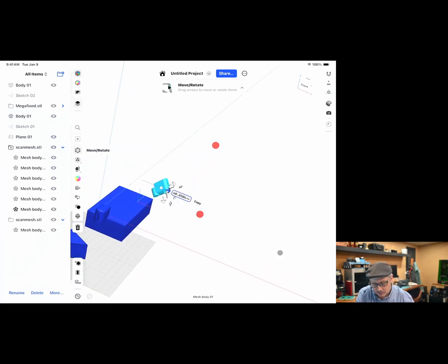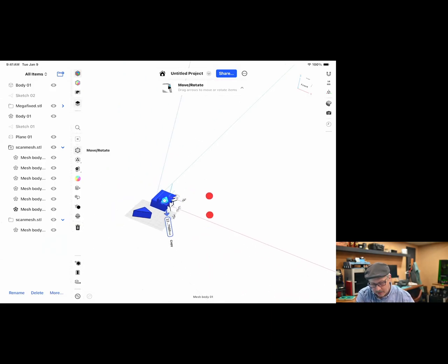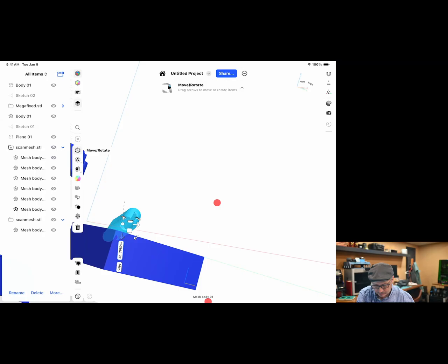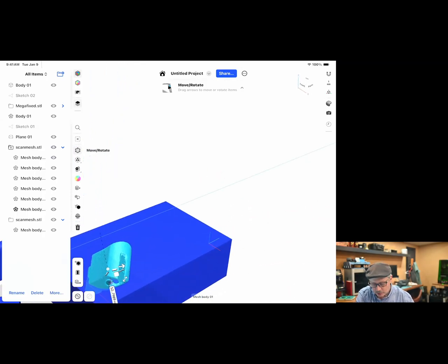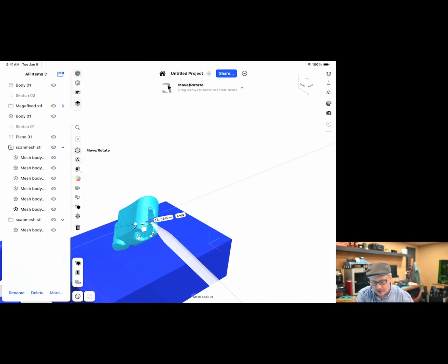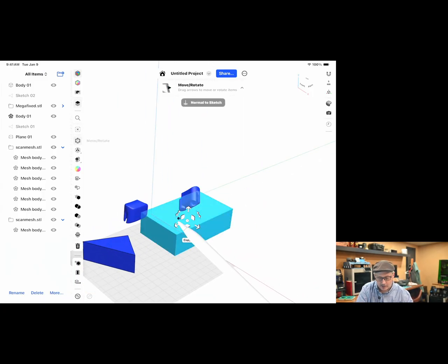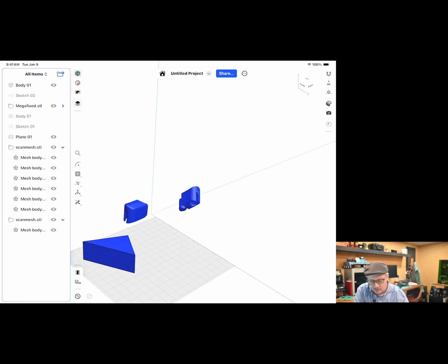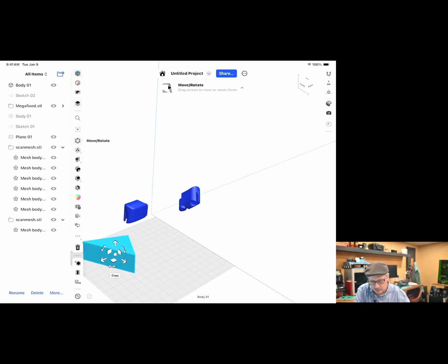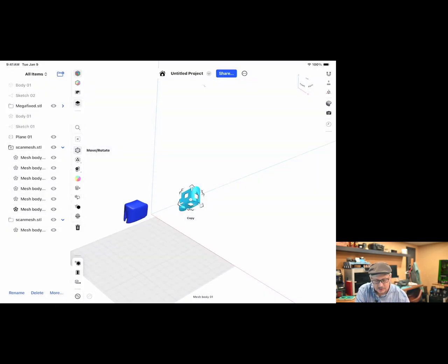Okay, if I come over here and take this non-manifold item, I can't really trick Shaper into taking this mesh drawing and making it into a step file. So what would be ideal is to project it on this plane. Let's take this guy, because that would make sense: we take this mesh object, see what its shadow looks like, and then trace that for vectors.